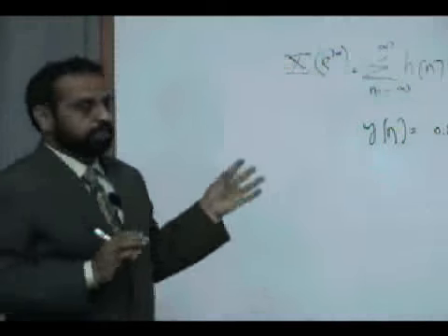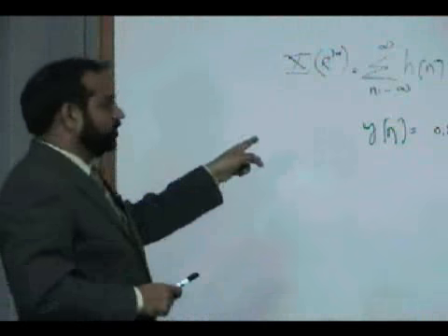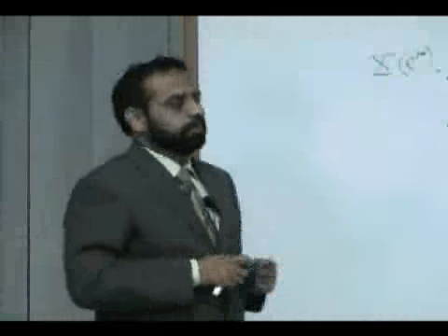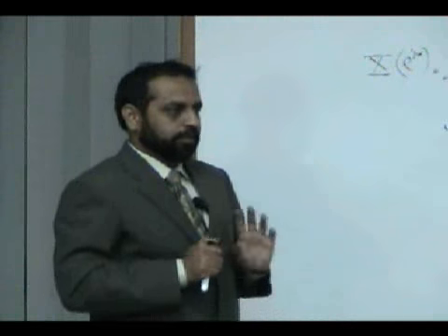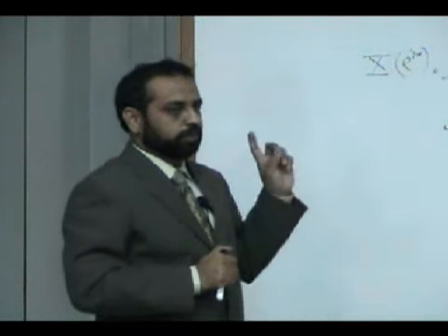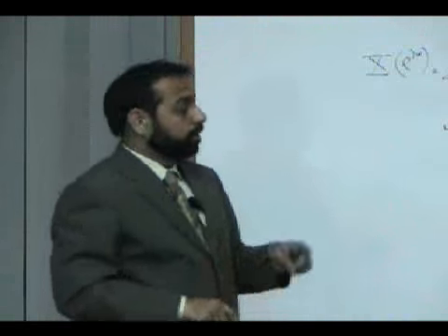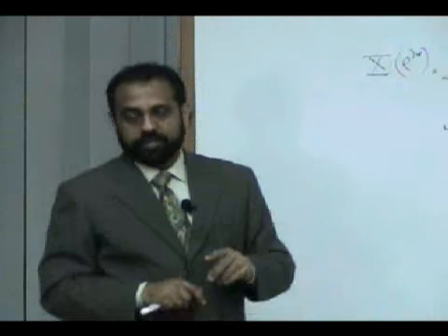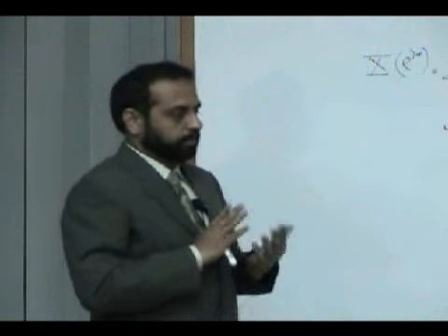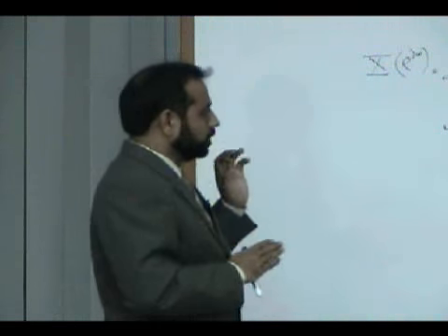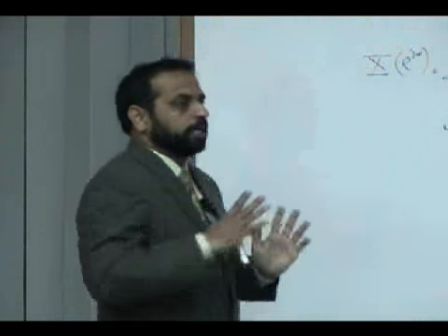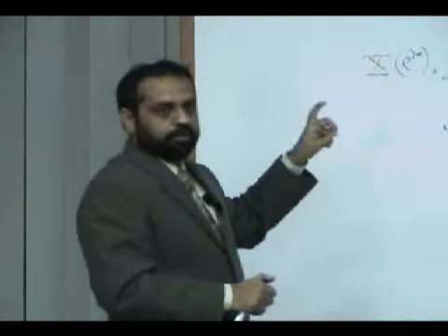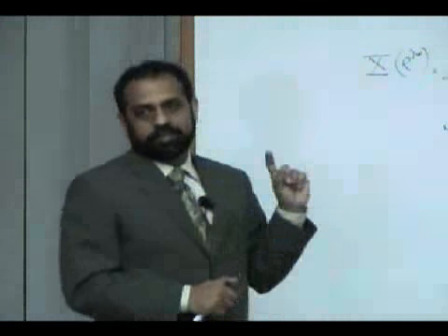So we know this is the objective: looking at the difference equation, find out quickly whether a system is stable or not. Z transform is used to comment on the stability by looking at the difference equation of an IIR system. That is the rationale of using Z transform. So now we'll see how we actually get to the point where, by looking at it, we say this is a stable or an unstable system.